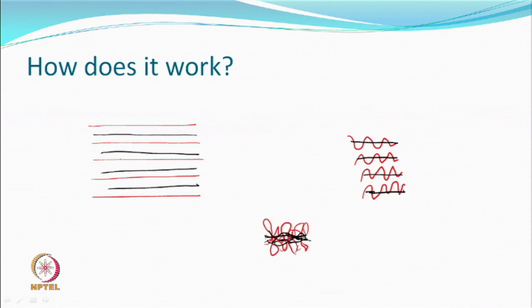Then in the case of a spun yarn, you might just see the yarn before the bulk generation looked a mix of black and red. At the end of the bulking process, the yarn may appear more red, because it is a non-shrinkable component, it has made loops, it is the one which is bending, it has come out and makes the sheath of the yarn, while the shrinkable component shrinks and goes more or less to the core.